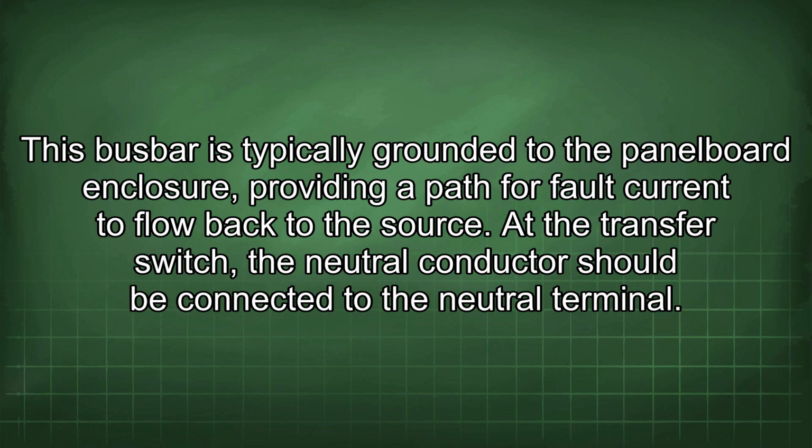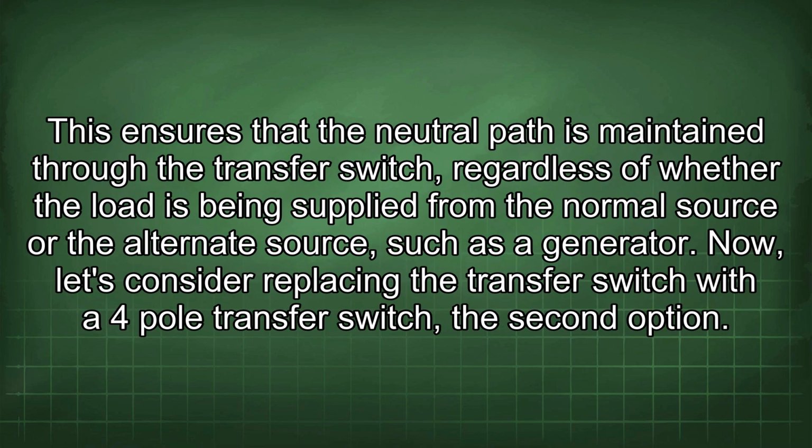the source. At the transfer switch, the neutral conductor should be connected to the neutral terminal. This ensures that the neutral path is maintained through the transfer switch, regardless of whether the load is being supplied from the normal source or the alternate source, such as a generator.